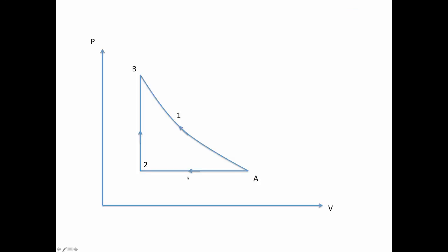I want to make one final point. If you want to go from state A to state B of a gas, where state A is at a lower pressure and a higher volume, and state B is at a lower volume and a higher pressure, there are a number of ways you could do it. You could go up along an adiabat. In other words, you could insulate your box, push in your piston and compress the gas. Or you could leave it uninsulated, and compress it while keeping the pressure constant, which would mean that all the time you're compressing it, you're also allowing heat to flow out of the gas. And then you could keep the volume constant and raise the pressure by adding heat into the gas again. So there are different ways of getting from A to B.